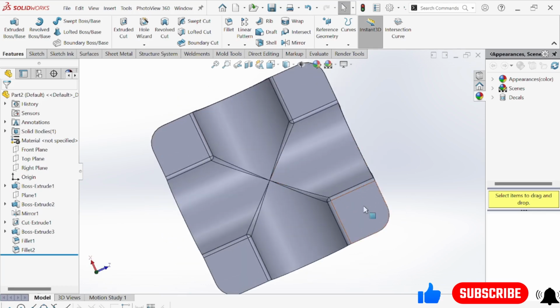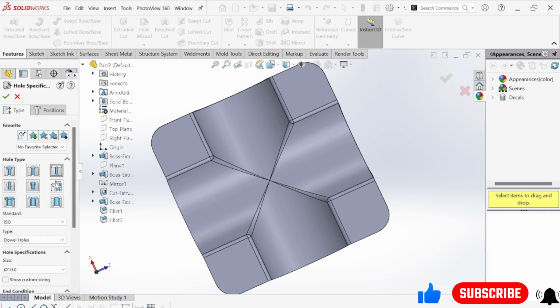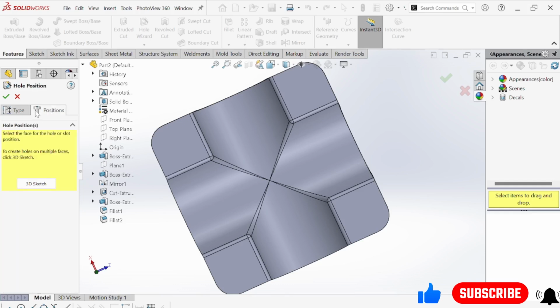Now we need to make some holes here. So how? Go to hole wizard. Simply select the third option. Drill size is 10 mm. It means 1 centimeter. You can also make this one 5. I think 5 is fine. Simply select 5 and go to position.